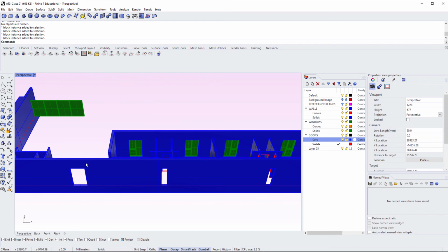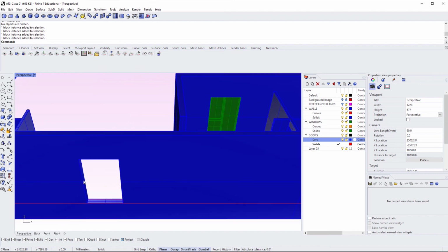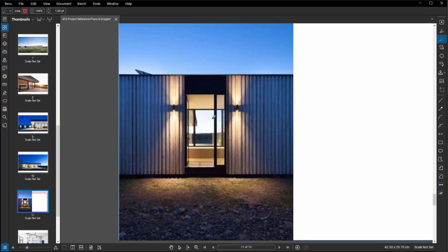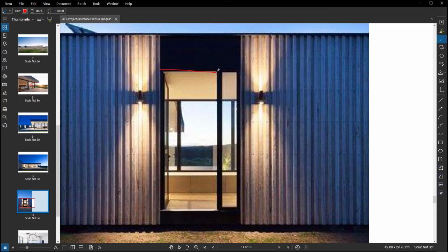And then as for your front door, you can have a little bit more freedom there in terms of how you want to design it. If you look at the example, you've got like a front door itself, and then you've got the side light. So generally speaking, the width of this, we've allowed 1.5 meters, and you may decide to say, all right, well then my actual door itself is going to be 1.2 wide or 1200 wide, and this might be 300, or you might say this might be a meter wide and this could be 500 wide. It's up to you. I'll leave that up to you and how you want to design that.